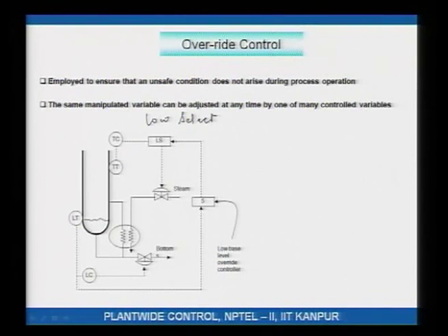So, to prevent that, if the level is going down and is continually going down even as this valve has fully closed, you would like that the steam be reduced. You would like to pinch the steam valve. So, if level is decreasing and it continues to decrease, steam valve must be pinched.